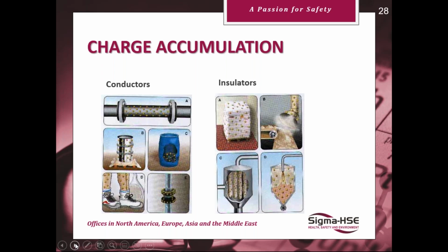In the other case, you've got metal isolated parts there, like donuts. They're isolated, not earthed, and again you get the same thing like A, but in reverse. These build up the charge, and if there is any earth nearby, then they will discharge to that earth. With insulators, they hold their charge and they can build it and keep it. So shrink wrap, for instance, going round, again, it won't lose its charge because it's an insulator.